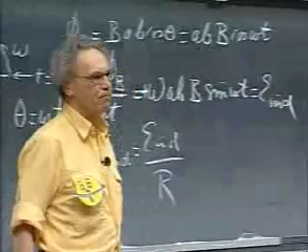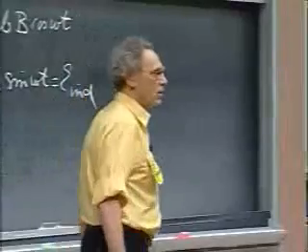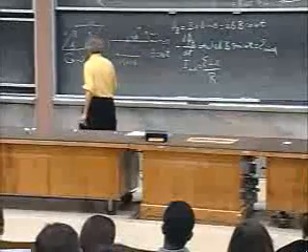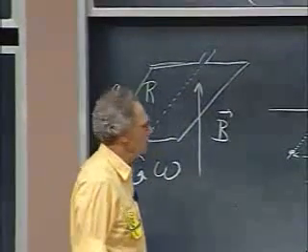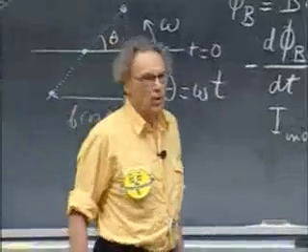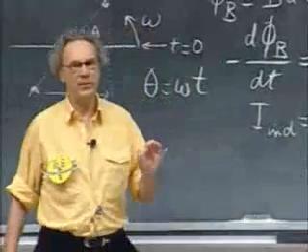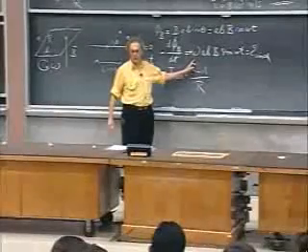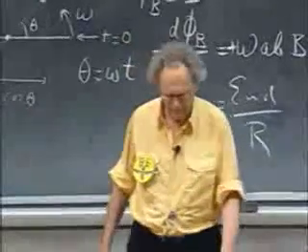You build motors, and during the prize ceremony I told you that the faster your motor rotates, the larger an induced EMF is, which is generated in the loop. You had a magnetic field, which let's assume is more or less constant. Of course, it wasn't in your case, but let's assume for the sake of argument. And as your motor was going to rotate, there was an induced current generated by Mr. Faraday, which is proportional to omega. So the current is larger when your motor goes faster. And that induced current opposes the current which was produced by your battery.